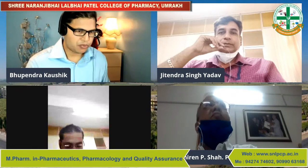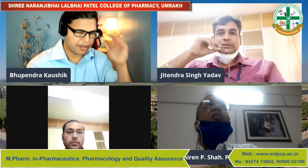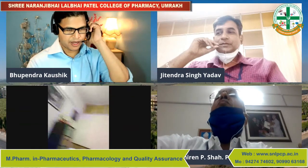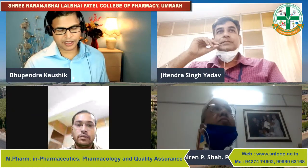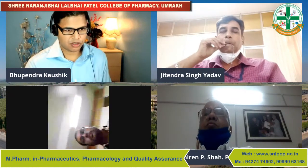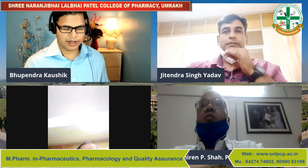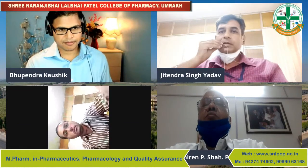It will, because what happens in a granulation process is basically different excipients coming in contact with water, and the rate at which they come in contact with water is important, because some of the excipients could be water loving, so they would probably get absorbed quickly, and others may take time. But if you have added too much water too quickly, then the distribution of water may not be uniform, and that is where the rate of addition of water plays a crucial role, and ultimately can impact the quality of the granule.